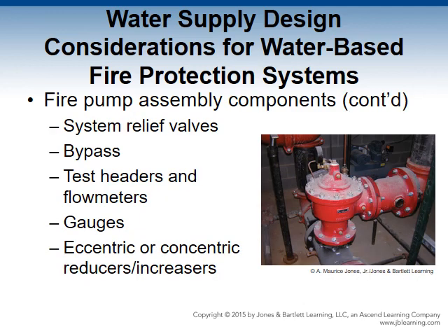Fire pump operation. A fire pump operates when there is sufficient loss of water pressure in the connected fire protection system. Both jockey and fire pumps detect pressure changes through 1/2 inch nominal size pressure sensing steel pipes or tubes that tap into the piping between each pump discharge, check valve, and discharge control valve. The pressure setting that signals the jockey pump to start is the churn pressure of the fire pump plus the incoming water supply pressure minus 10.